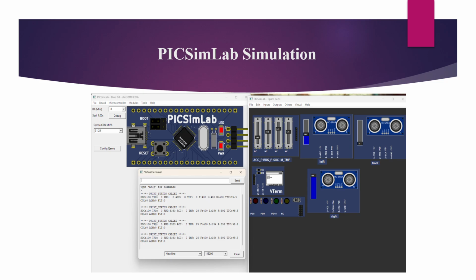Then next is PiximLab simulation. This slide shows the PiximLab simulation. PiximLab provides a virtual STM32 development board where we can test our firmware without using physical hardware. It allows us to simulate switches, LEDs, sensors, and serial communication. This makes debugging easier and reduces hardware dependency during development.